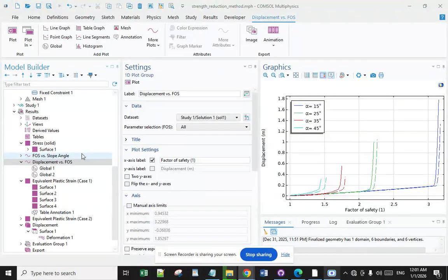Example and interpretation. If the FOS is equal to 1, failure occurs exactly at the design load, unacceptable for most applications. If FOS is equal to 2.25, a chair designed to hold 360 pounds is used by someone weighing 160 pounds, which means 360 divided by 160 is equal to 2.25, meaning it's 2.25 times stronger than needed for that person.